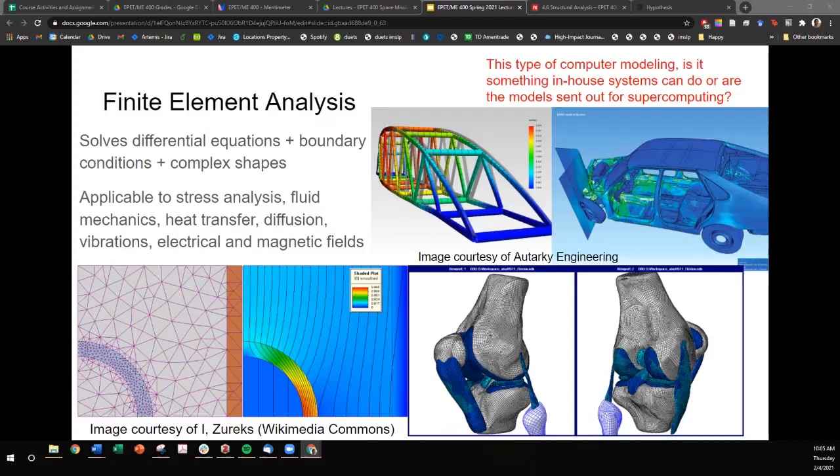Those hand calculations are sufficient if the load path is easily determined and straightforward and the flight loads are well characterized, right? But what if we had a structural component with a more complex shape? Or the load path was not directly axial or shear or torsional? What if there are multiple forces or boundary conditions? Then we have to look at how micro interactions sum up into a macro response.